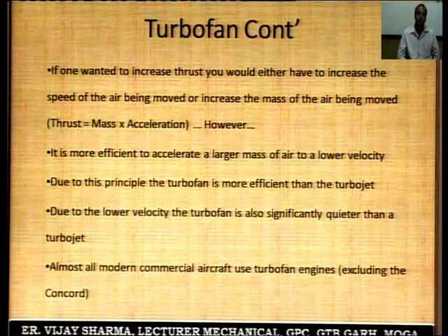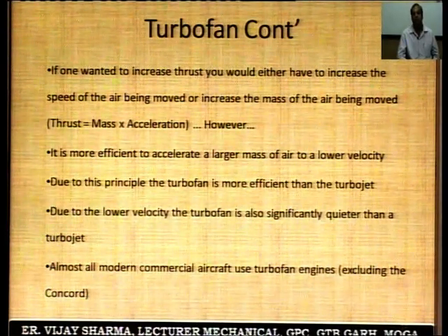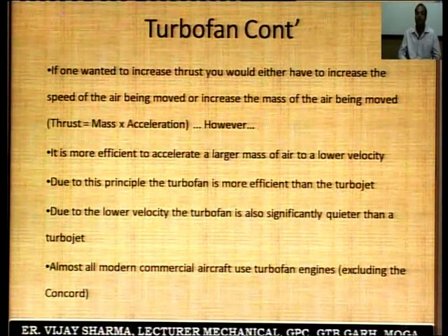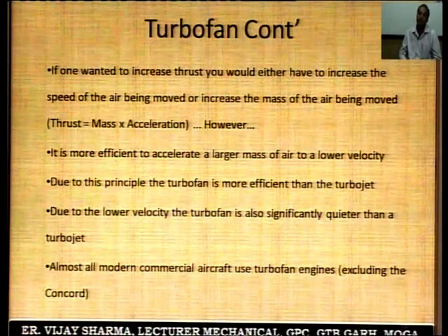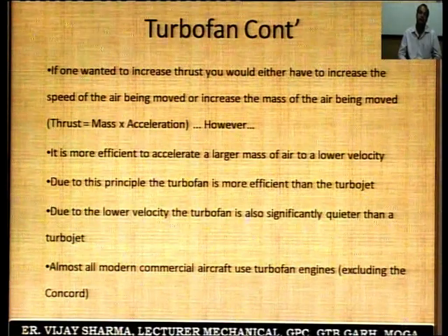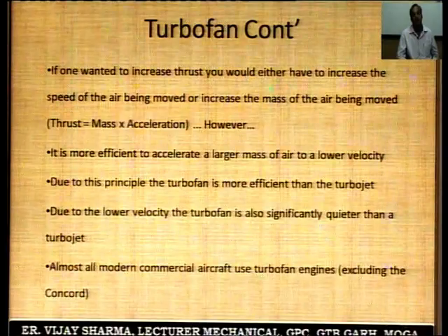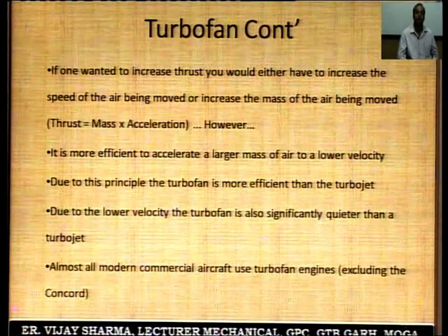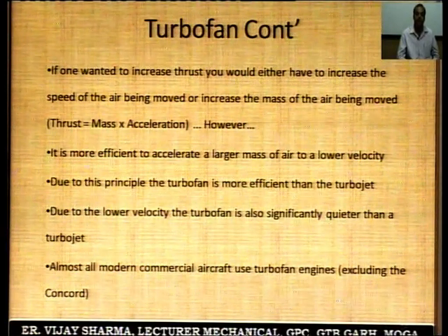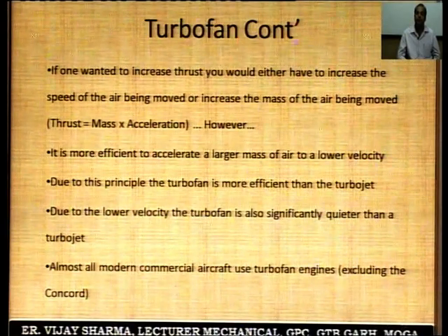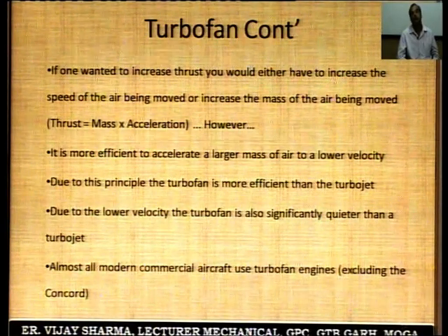Third, due to this principle, the turbofan is more efficient than the turbojet engine. This is the main basic advantage of the turbofan engine over the turbojet engine. The next point is, due to the lower velocity, the turbofan is also significantly quieter than the turbojet engines.